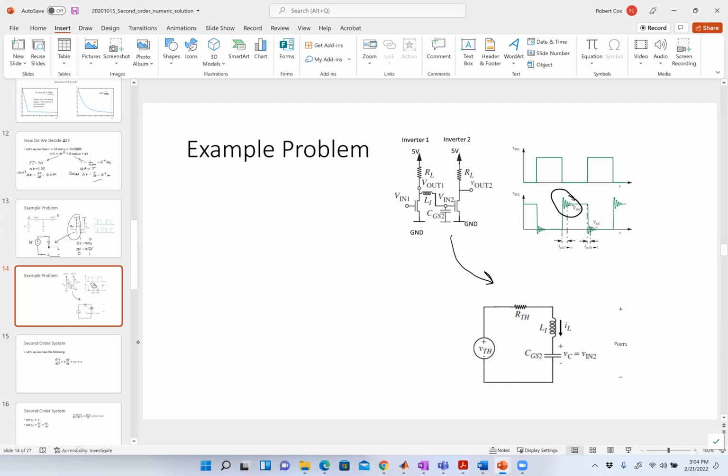Now, what do you guys call that? That's a second order system. And if I get that kind of behavior like I have in that picture right there, so which one is it? Underdamped. All right. Oftentimes from a design perspective, I say that circuit rings because it acts like a bell. If I ring a bell it gives me a tone, so it rings like a bell. All right. So we say that circuit's ringing. It's an underdamped response.